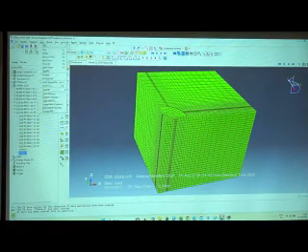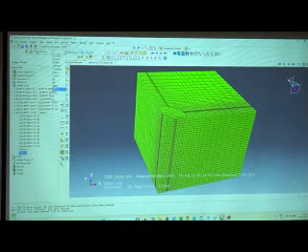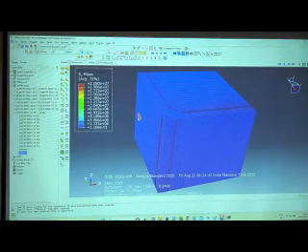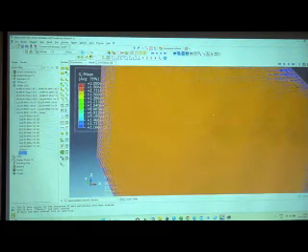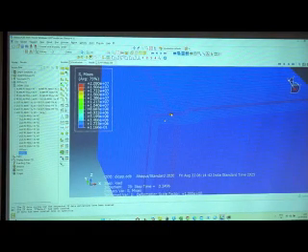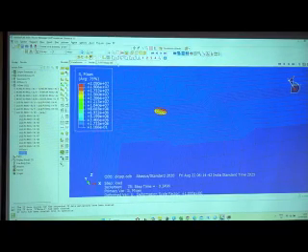Stresses like the Mises stresses, Mises doesn't show in prescribed displacement. It shows only if you apply the pressure. I will show you. Change it, remove the concrete body. See, it doesn't show. It's showing in the pile. That means your stress is very minimum. You just need to adjust your axis range.